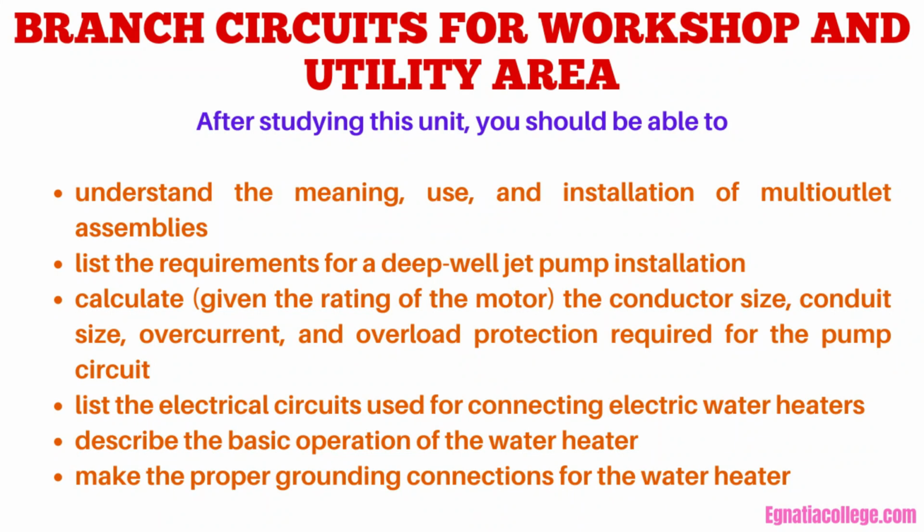After studying this unit, you should be able to understand the meaning, use, and installation of multi-outlet assemblies. List the requirements for a deep well jet pump installation. Calculate, given the rating of the motor, the conductor size, conduit size, overcurrent, and overload protection required for the pump circuit. List the electrical circuits used for connecting electric water heaters. Describe the basic operation of the water heater. Make the proper grounding connections for the water heater.